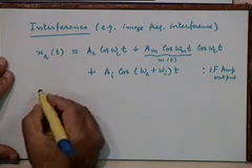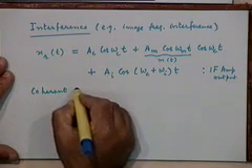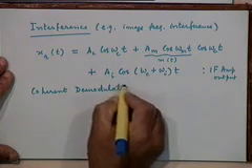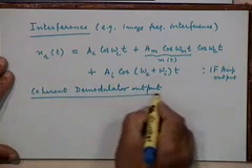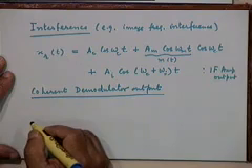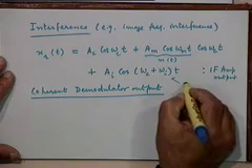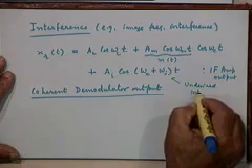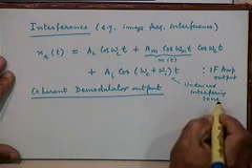So suppose we have coherent, before we talk about diode detector, let us talk about coherent detector. What would the coherent demodulator produce? Right? So remember, this is the undesired interfering tone. So both omega_c plus omega_I and omega_c will be translated to the same frequency omega_IF.